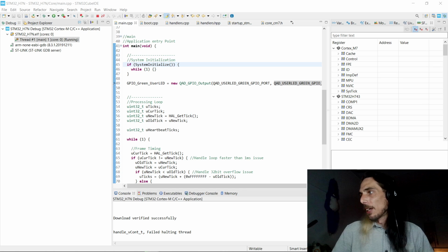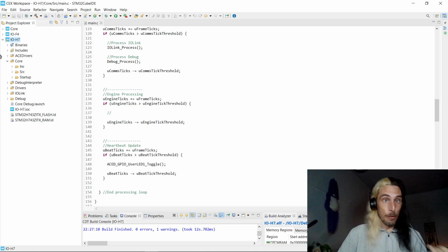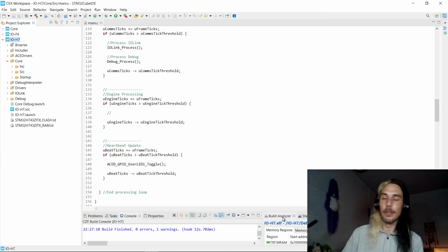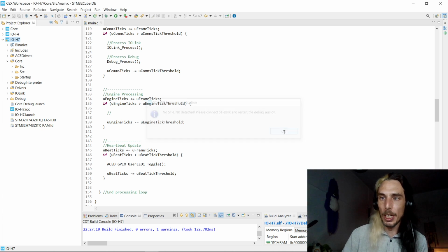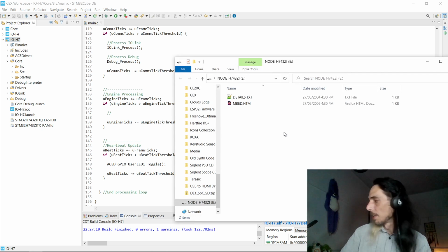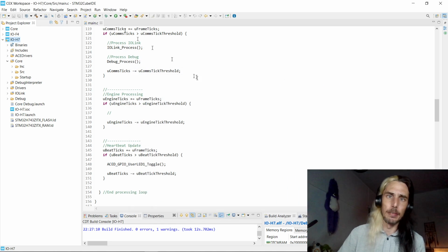Now, just to make sure that the board itself doesn't have an issue, what we can do is actually take some old code from another project where the H7 was being used, and dump that on there and make sure that it works as it should, just so that we can confirm that the issue is definitely our actual code rather than the board itself. It's pretty unlikely that it's going to be a hardware failure, but it's always good to just rule that out.